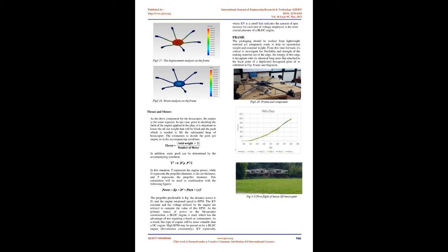F, results summary. With the replacement of aluminum with carbon fiber, we got a reduction in structural weight by nearly 42%. That reduced structural weight got added in the payload as increased efficiency. Also, the designs we opted for helped us increase the efficiency of our drones. In Monocopter, by using the aluminum the frame weight was estimated to be 775 gm. By replacing the material with carbon fiber, we got a weight of 450 gm. Thus, with the replacement of aluminum with carbon fiber, we got a reduction in structural weight by 325 gm.